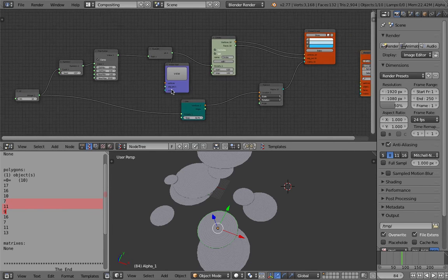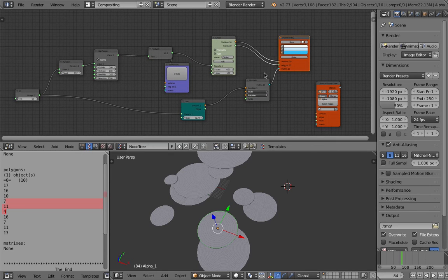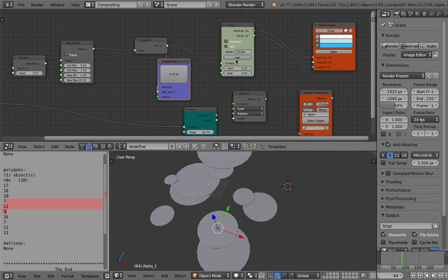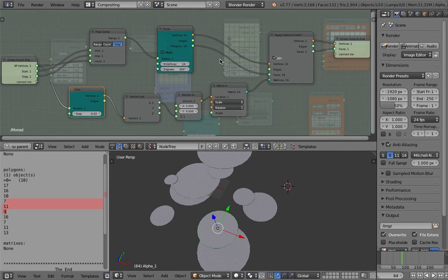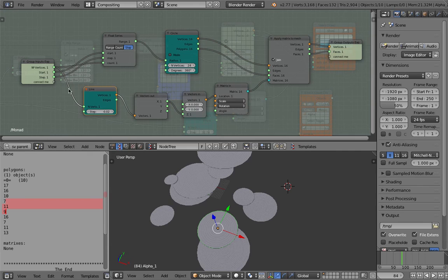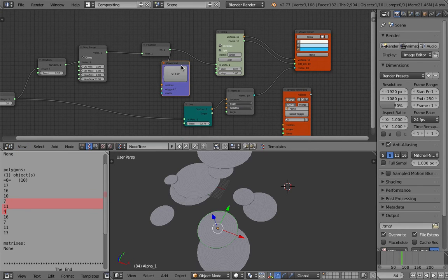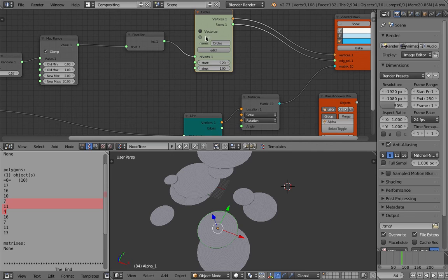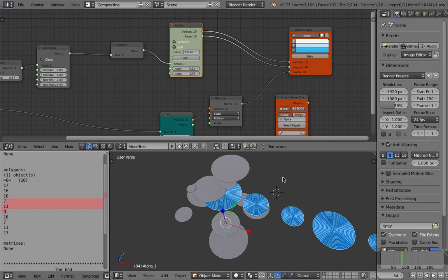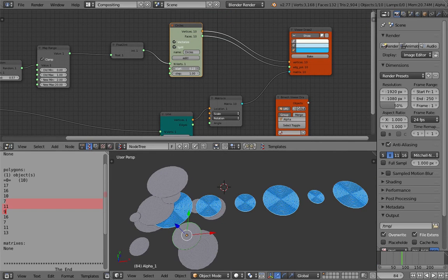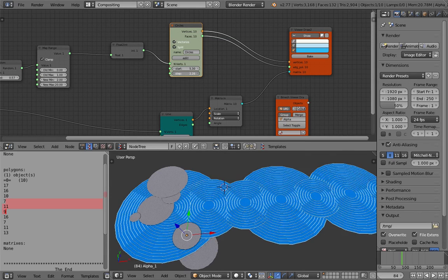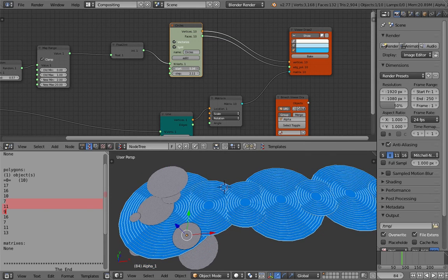It takes some thinking to understand the monad thing, but once you understand how to create the monad and then how to randomize it outside of the monad and then turn on the vectorize and split, this becomes really powerful. Yeah, so there you go.